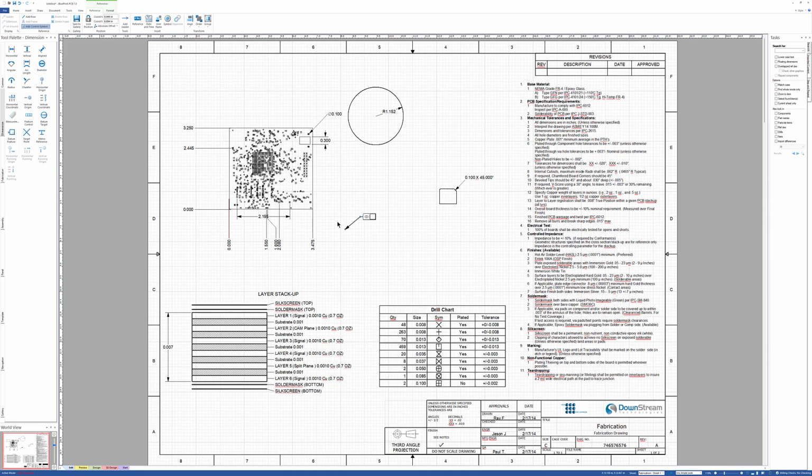There's actually a ratio that has to be maintained between that little piece of information in there and the size of the box. And you can add items to your particular feature control frame. You can insert other boxes, that sort of thing, delete them. It doesn't have to be a composite frame. It can be any rectangular type shape that you want there.